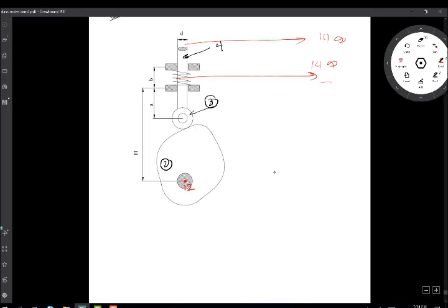So if I connect this to 1, 4 at infinity, I get a locus of 2, 4, as simple as that. It doesn't matter where you draw this one. Now this point is a rolling contact. This has to be 2, 3, and the center here is 3, 4, and when you connect them, you get another locus for 2, 4. And this point here is actually point 2, 4.